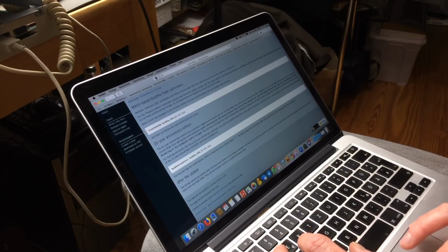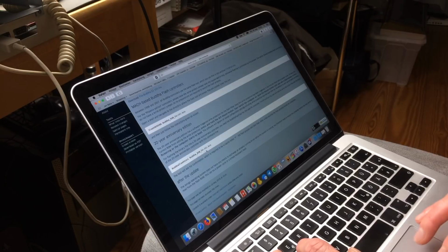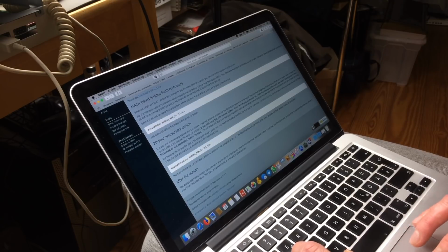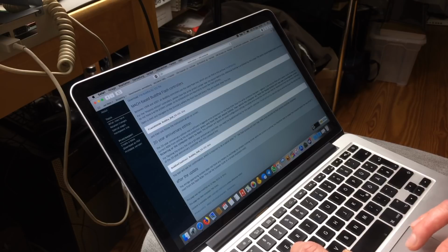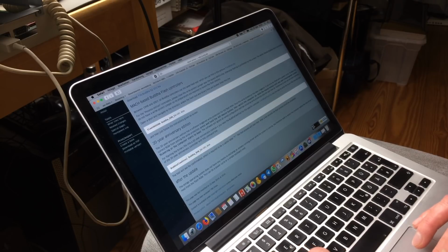Okay. And for the 20-year anniversary edition, which is what I have, it just says I use the Buddha Flash Tool command and specify the binary that should be used. 20-year has a software triggered write protection for the flash ROM. Once this write protection has been triggered, it can only be lifted with a power cycle. To keep the current ROM from setting the write protection, press and hold the left mouse button, then switch the computer on. Hold the mouse button until you see a black-green screen flickering or the computer starts to boot. The software will ignore all saved configuration settings, including write protection, and the wait time for hard disk to spin up and boot normally.